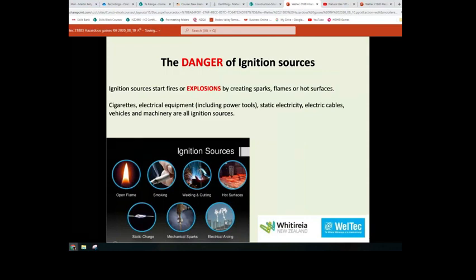For example, if you're in a house and you inadvertently create a gas leak because you left the uncapped end or something and turn the gas on, you wouldn't want to turn off a light switch. Turning it off can potentially create a small arc in the switch itself, which could ignite the gas. So you're better to leave something on than flip the switch.